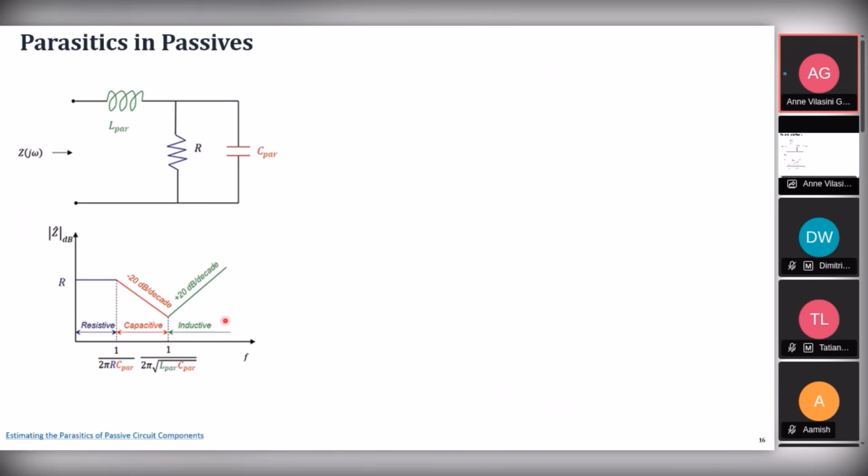So when you look at the impedance curve, which here you can see, at the lower frequency range is the only area where you see that the resistor is behaving as a resistor itself, which is what you expect. But when you're increasing in frequency, you can see that the resistor is becoming a capacitor. And when you increase the frequency further, it is no longer a capacitor nor a resistor, it becomes an inductor. So the same component has three different behaviors depending on the frequency of operation.